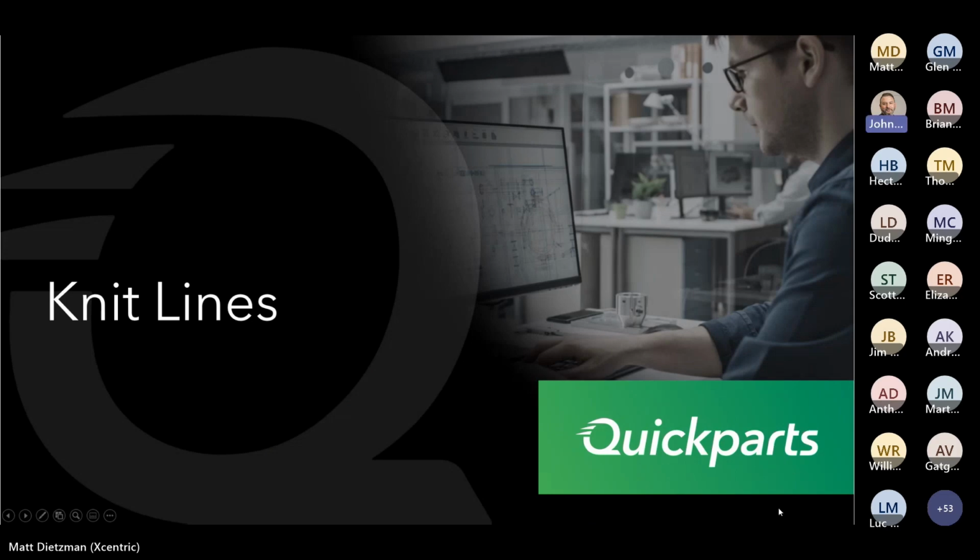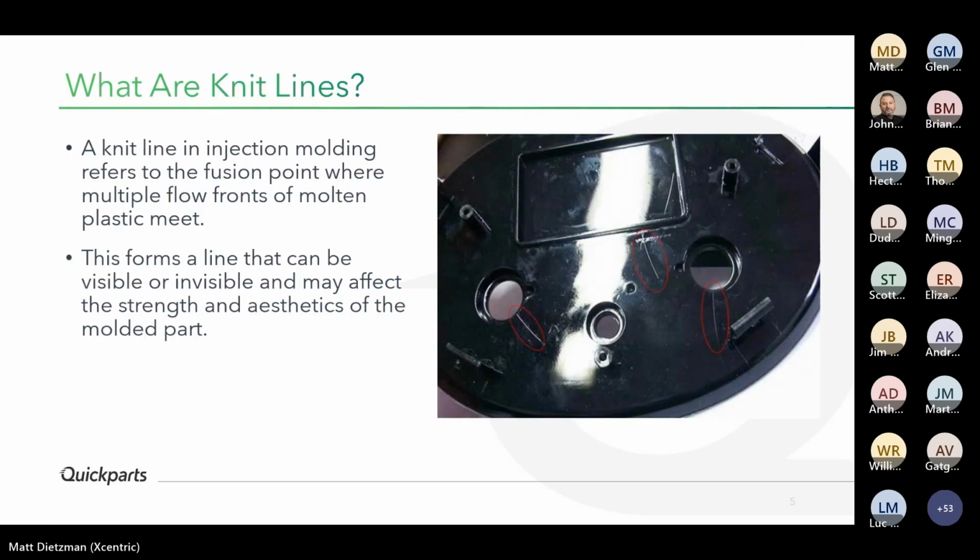So first, we'll start with knit lines. So what are knit lines? If you're not familiar with molding, a knit line in an injection molded part is really referring to a point where you have two molten plastic flow fronts meeting together.